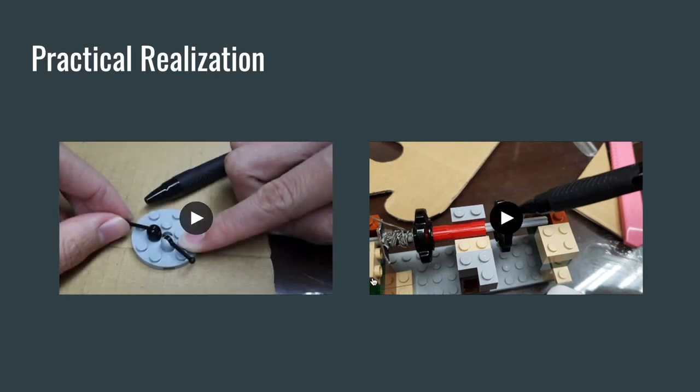Second, the movable rotary gears. Since we have to make the axis of the gear rotatable, we could not fix it. However, while this axis rotates, it would move horizontally. That made one of the legs at the bottom of the pendulum unable to push its corresponding teeth. Hence, the clock stopped moving.